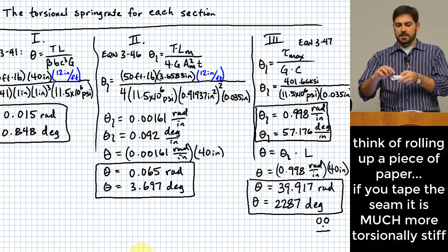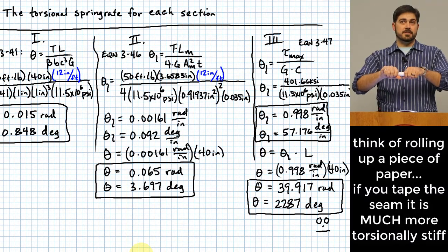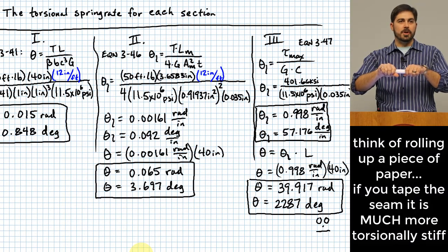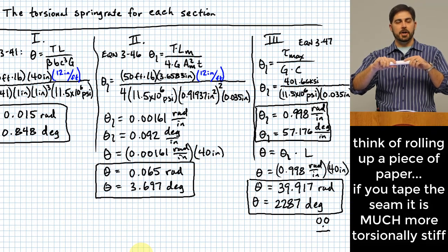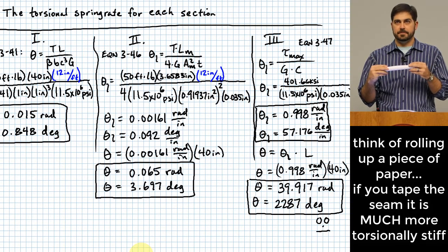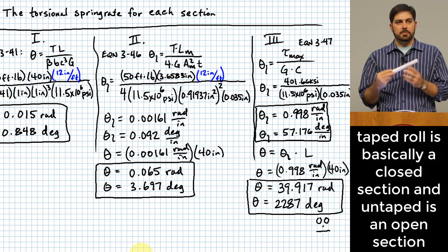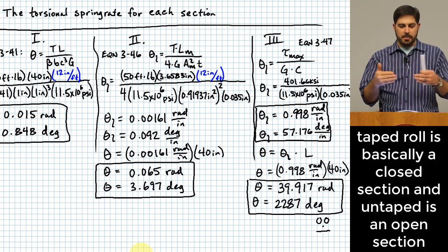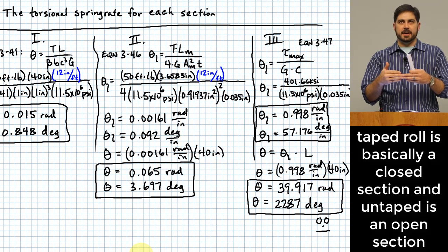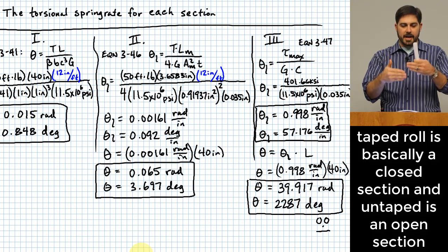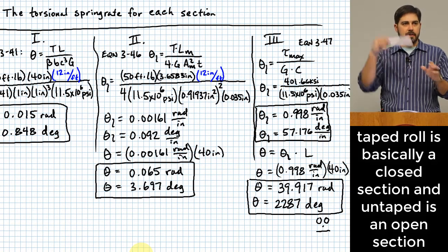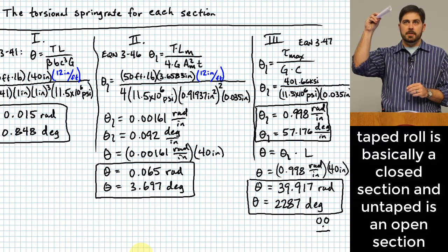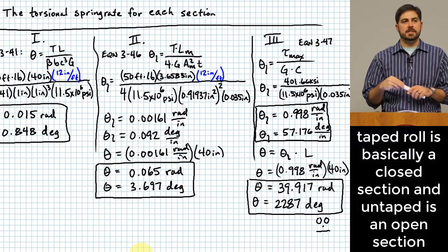Okay. If you do that and then try to twist it, you will find that it will support a lot more load in that torsional direction. That is the same exact principle as what we've dealt with right here. By closing that cross-section, you're making sure that the ends of that membrane are not allowed to move relative to one another down the length of the member that's carrying torsion. And by doing that, you greatly, greatly stiffen it and make it stronger.